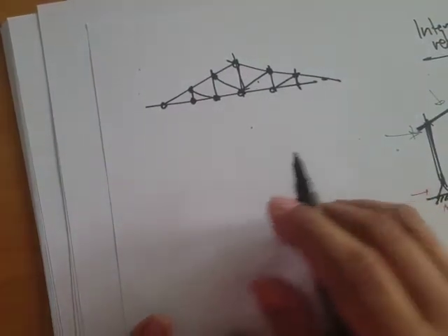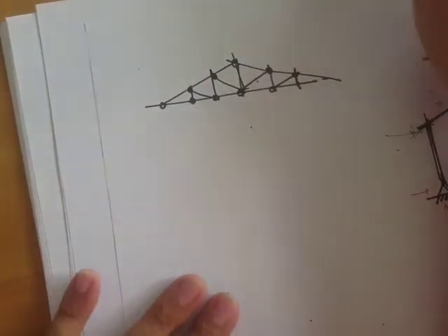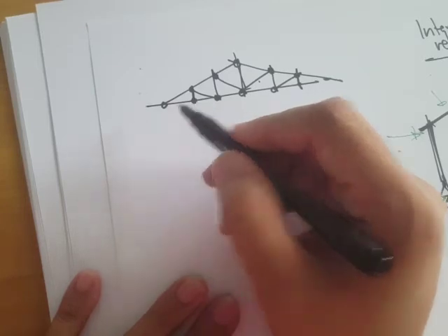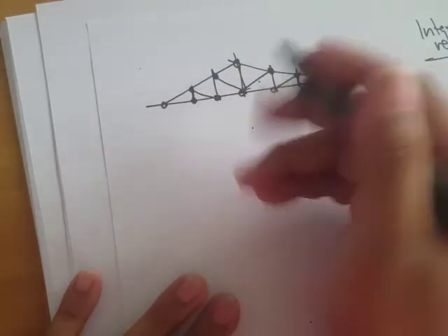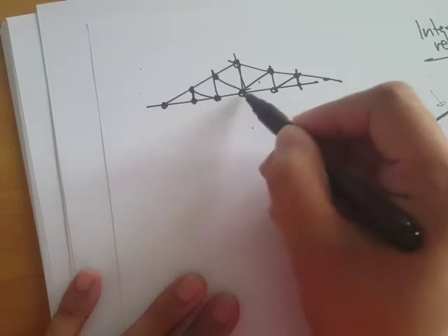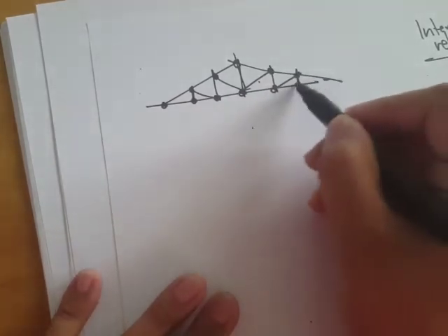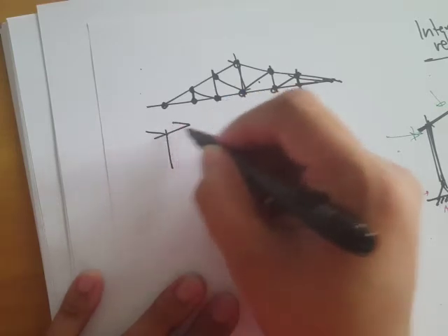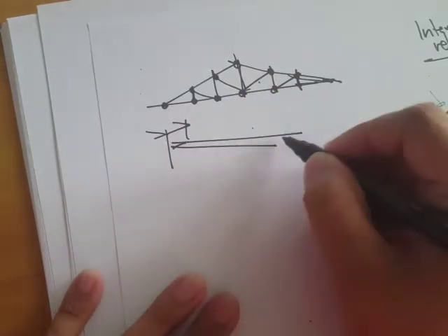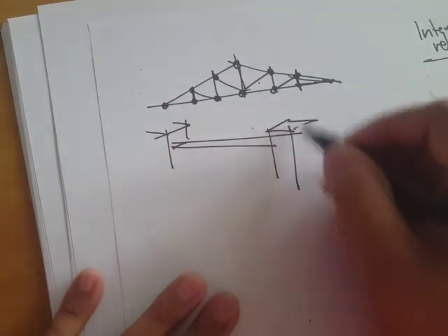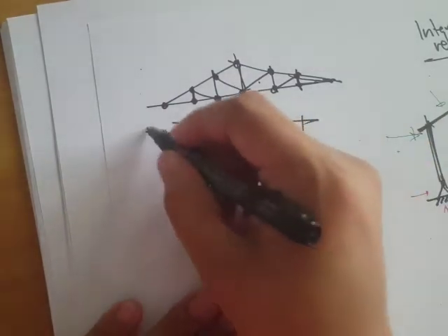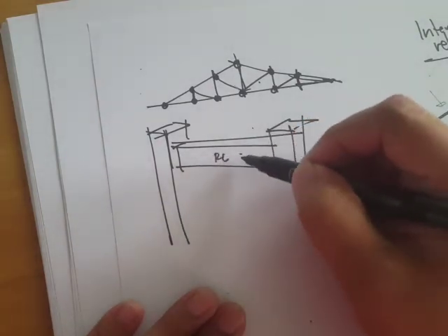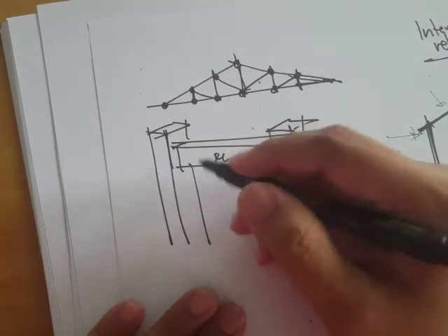We'll continue now with the applications of these structural supports. As I've said, the trusses are actually fixed supports, but we analyze them as pin supports or internal hinges. Fixed supports are actually common in reinforced concrete columns and the joints between reinforced concrete beams and reinforced concrete columns.